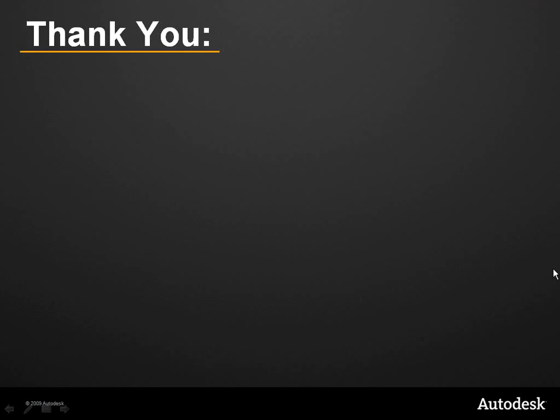And it's a little thing on that dialog. It's the name of that projection. And in our help, you can look at it for importing points. Look at help. I can't remember the exact syntax, but I believe in the very header of the text file, you put in that CA for California, NAD 83, Zone 5. Whatever it says on that dialog, and the help clarifies it. It's extremely easy to do this.